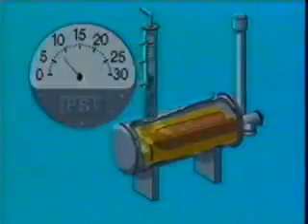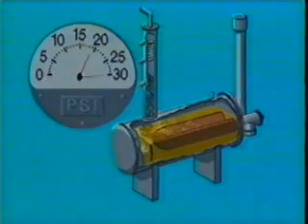Regenerator pressure will build up if there's a plugging or flooding problem in the still packing. An increase in regenerator pressure prevents some water from boiling out of the glycol, requiring higher temperatures in the reboiler. This wastes fuel gas and can lead to glycol degradation.